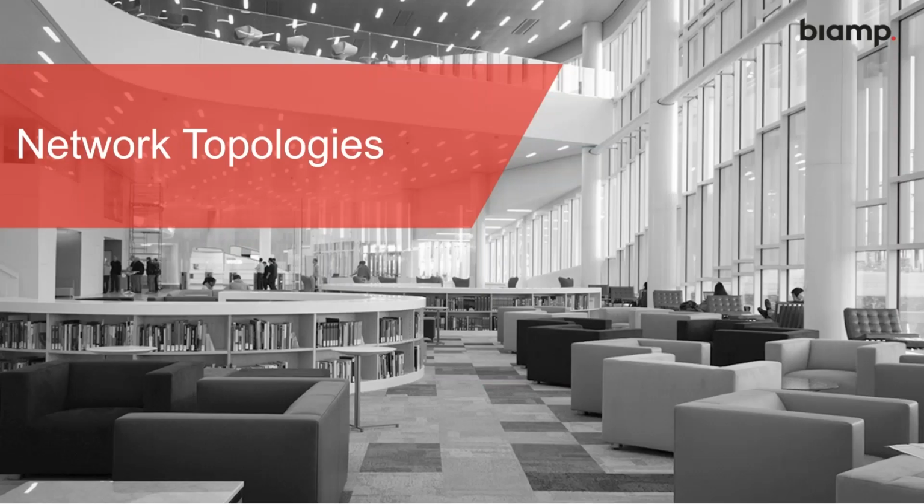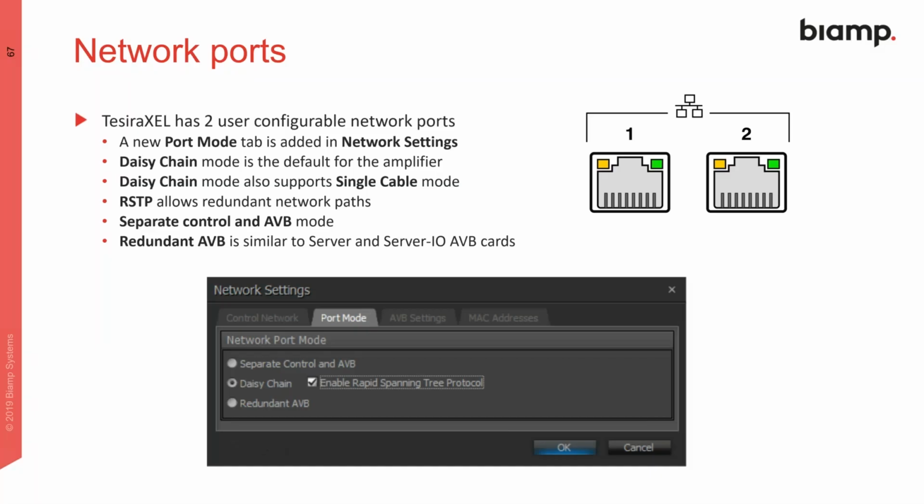All right, our final deep dive. We're going to get into some network topologies real fast here. Network ports, we have 2 ports on this device. They are an AVB switch. We've got daisy chain as the default mode, so we can just chain amplifiers together. It also supports single cable mode. When it's in that mode, you just plug in channel 1 or port 1, and you can discover. RSTP allows for redundant signal paths, so we can allow that to route. We can make loops, and it won't break the network.